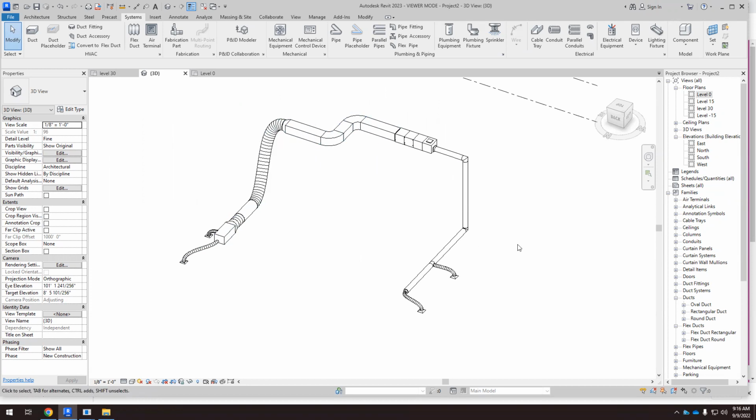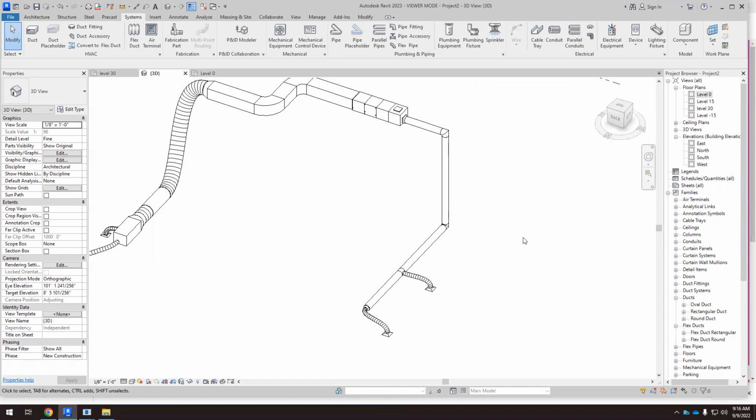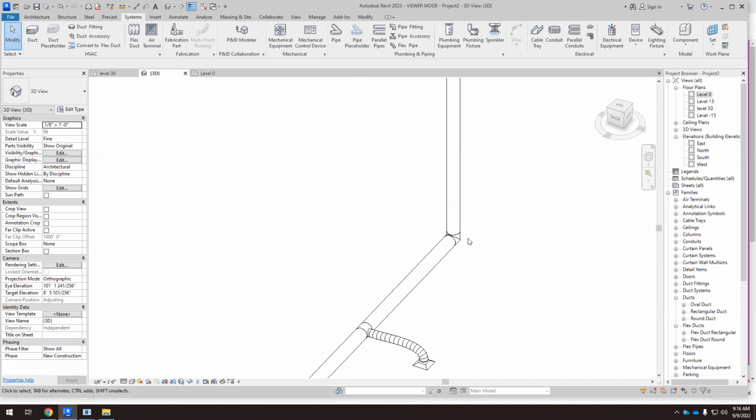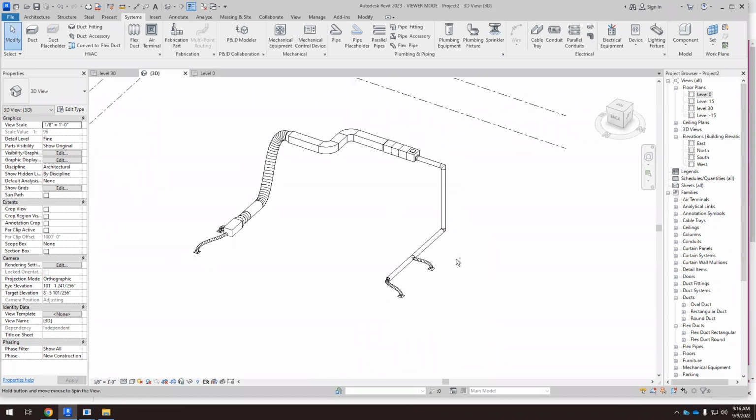But this is much better because we have reduced the length of the ducts, and we have reduced the transitions, round to square, reduction from 40 inches to 20 inches. So we have to do that. Eventually, in big buildings, we have a lot of reductions, elbows, T's, all that stuff. But if we reduce the amount of things that we have, it's a better layout. So it's about simplifying things.